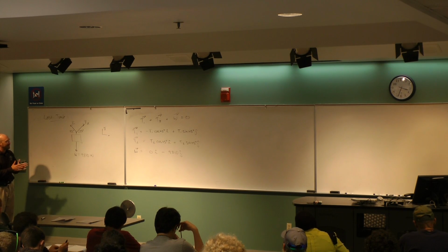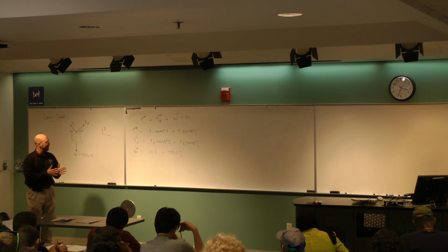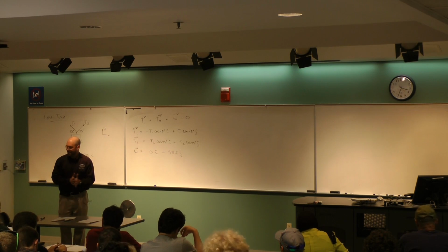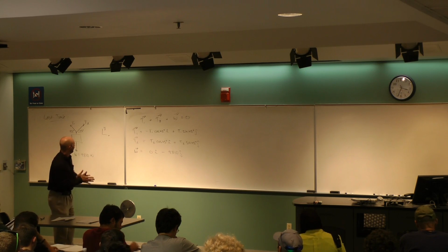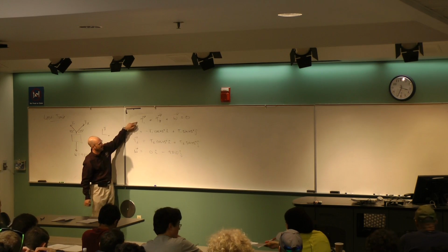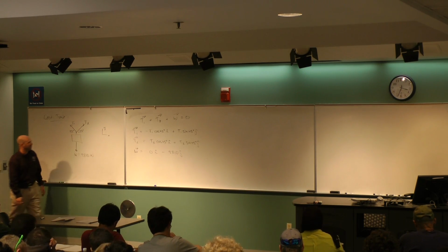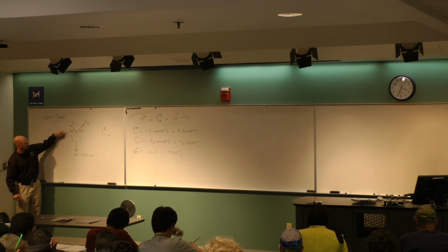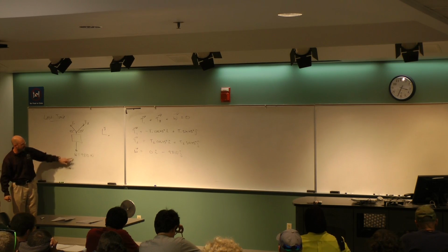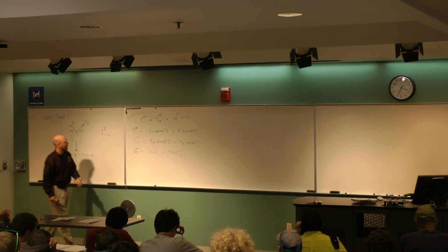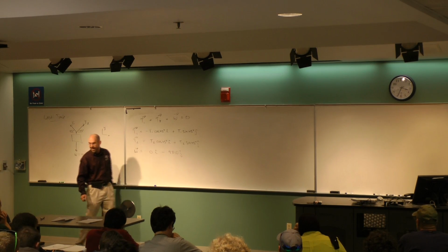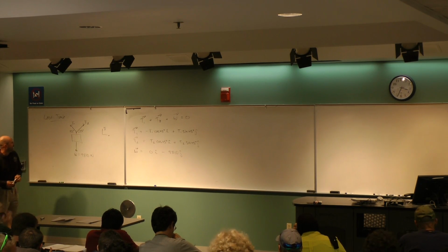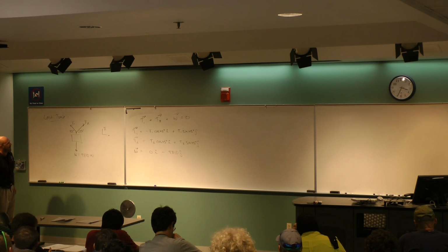Okay, and so the idea was that if I have static equilibrium, that means that when I add up the forces, I need to get 0. And so that's this equation right here: T1 plus T2 plus W equals 0. These are the two tensions. This is the W. And we talked about last time, step 1 is to write each one of these things down as a vector. And so I believe this is what we came up with.